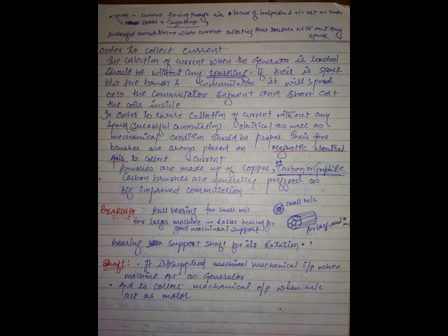What is this number 6 telling you? If you place the first coil side in the first slot, and if you place the other coil side of that coil in the 7th slot, you maintain 6 coil span. Maintain the coil span as 6, meaning 1 plus 6 is equal to 7.